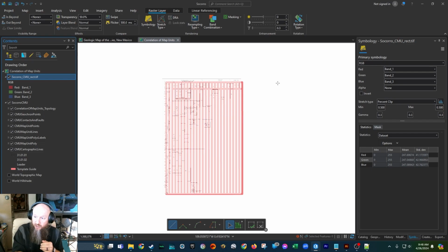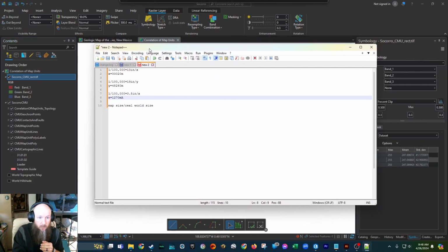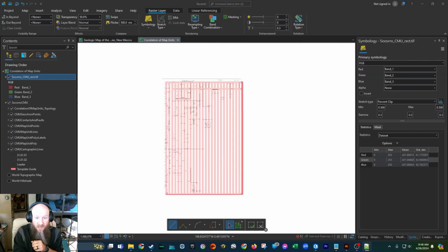Do the conversion to figure out what that box is at map scale. And once you have those numbers at map scale, you can go ahead and build a box that is that same size scaled for the 1/2 inch wide hand-drawn or designer program that you can then georeference to in ArcGIS.